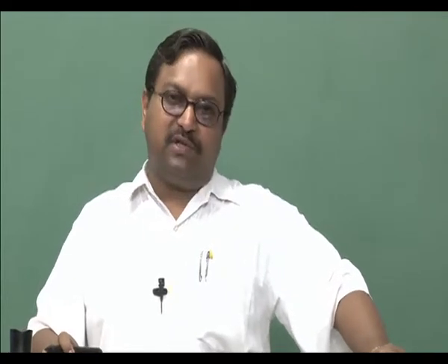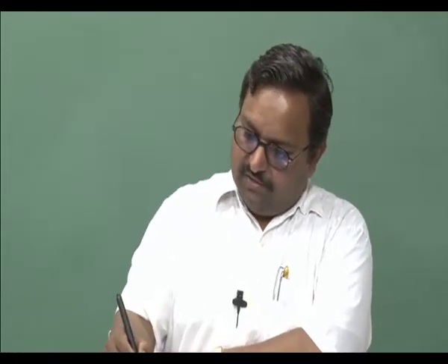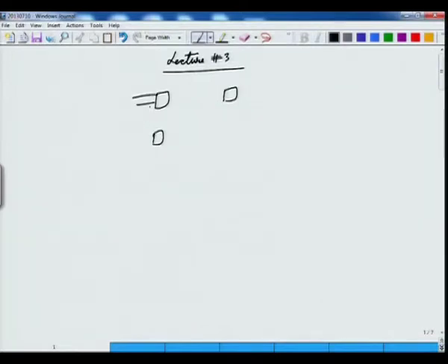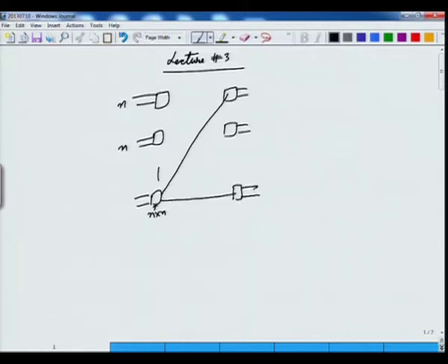First thing was the use of creating larger size by using a smaller thing, and further reducing the cross point complexity. So, what we did was I took a case where we were trying to build up using 2 stages, and I took some switch with a small n as the input ports, and then we built up the interconnect. If I am going to use n by n, I said that one link can go to each one of the switches in the output stage, or in the second stage, but this was leading to a blocking situation.